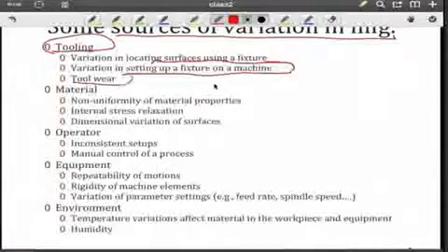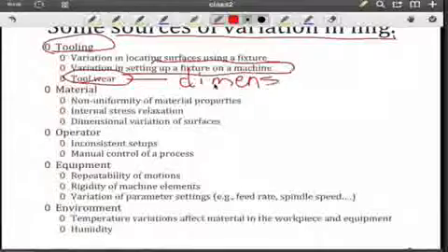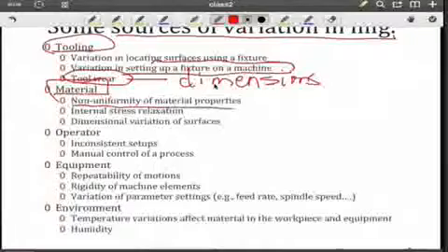And then, of course, we've got tooling that comes in contact with material. And when that happens, you know from IE 248 that tool wear can occur. And if tool wear occurs, then we know that has a direct effect on our dimensions. Material. So we have stock material that we order. And when I examine that material, you know from material science that material is not uniform.